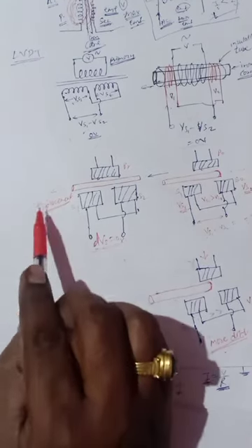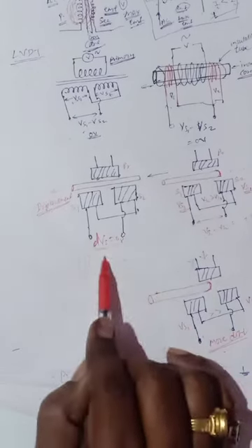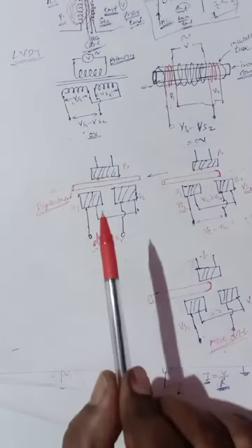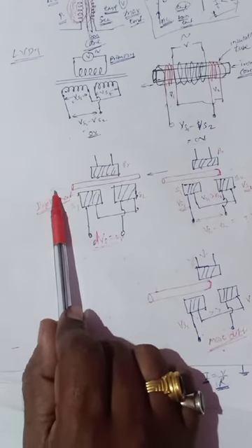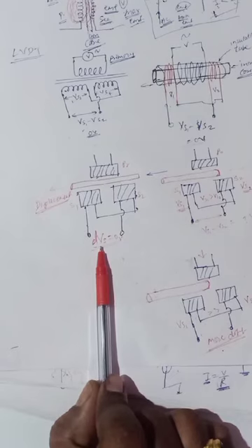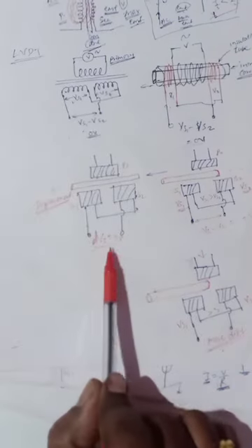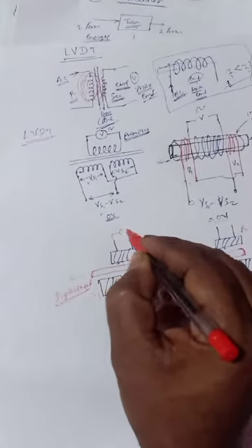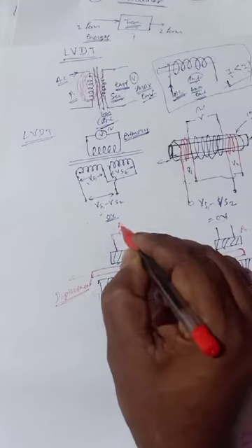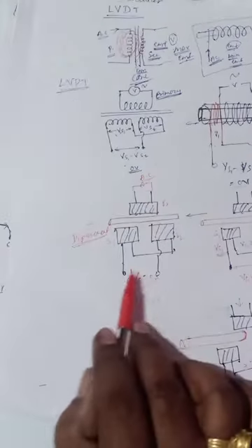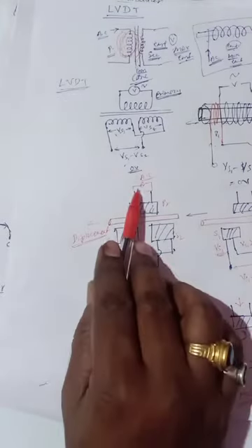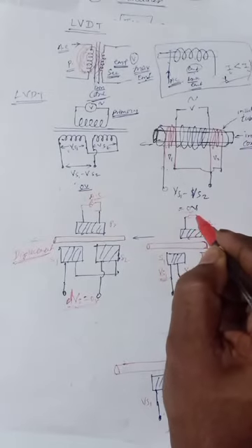It is just like a transducer. A transducer converts one type of energy into another type. But this transducer is a sensor which is used to convert displacement into voltage. Obviously this requires a primary voltage. Keep in mind that you have to apply some AC voltage to the primary, and only then you get this difference. Otherwise, if there is no voltage, we don't get the difference. So you have to apply the voltage, don't forget this.